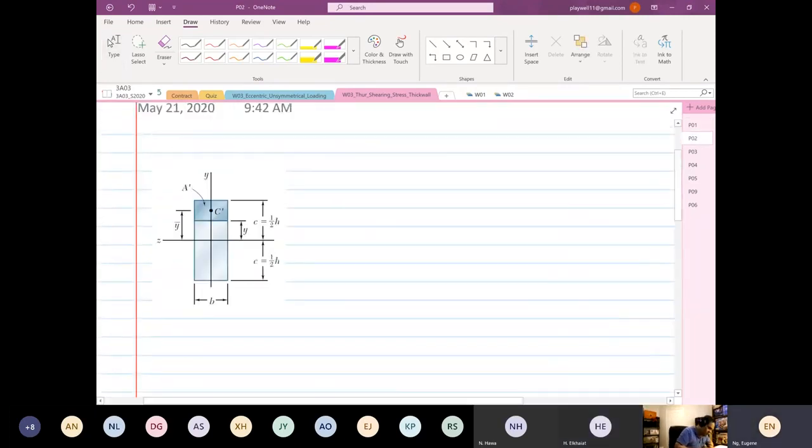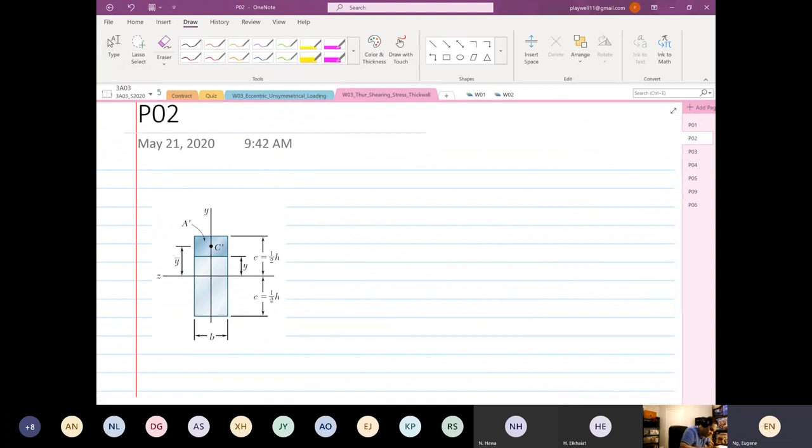So from here, again, our shear force is coming from Vy. The next thing we want to find is Izz, so the ZZ axis is of interest. Like I taught you before, parallel to the geometry in the ZZ, this is the width, and perpendicular, this is the depth.